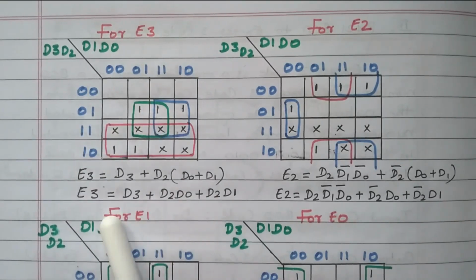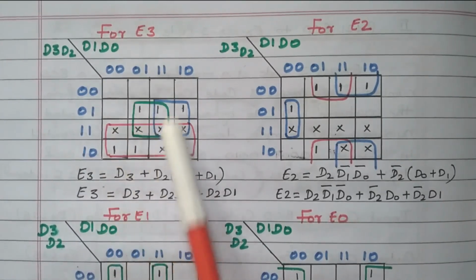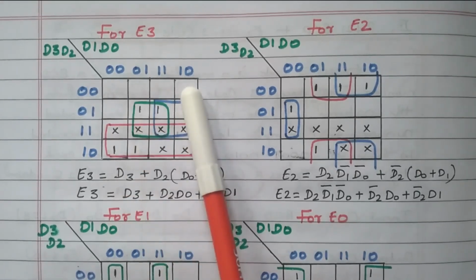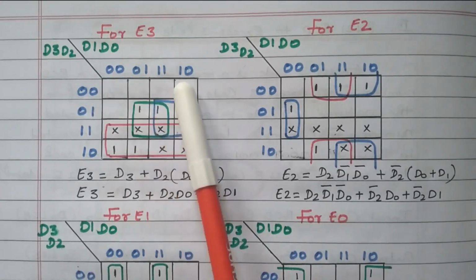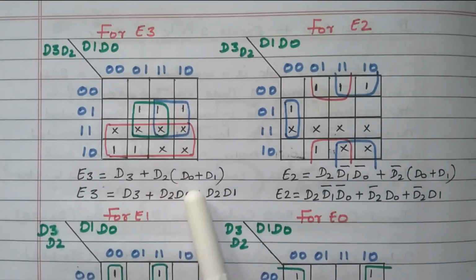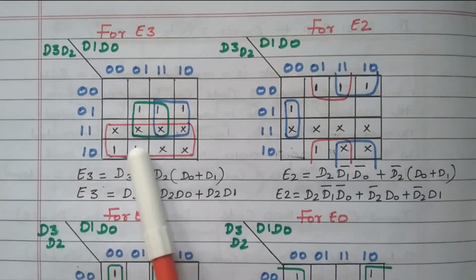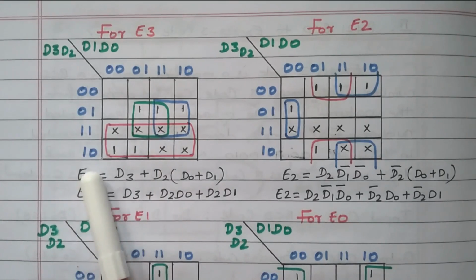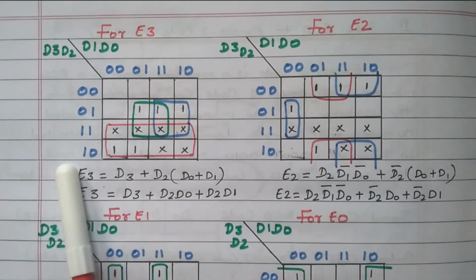While covering all 4 columns, 00 is cancelled by 11, and 01 is cancelled by 10, because here 0, here 1, here 10, here 00, 11, all are cancelled. Only the third and fourth rows we have to refer to. What is available in the third and fourth row? 11 and 10. See, this 1 is available commonly in the third and fourth row.